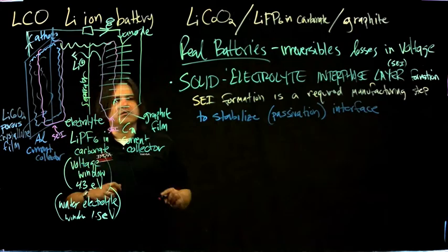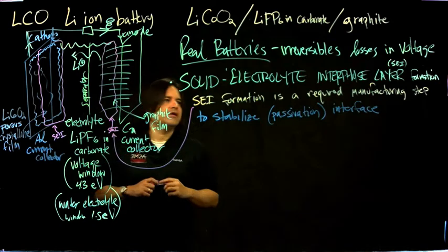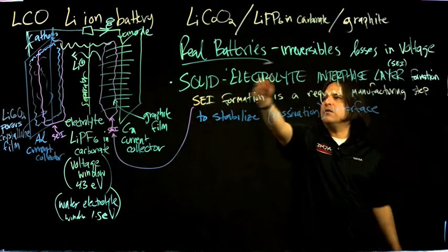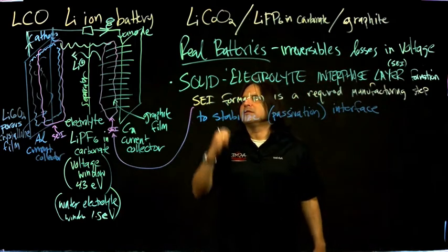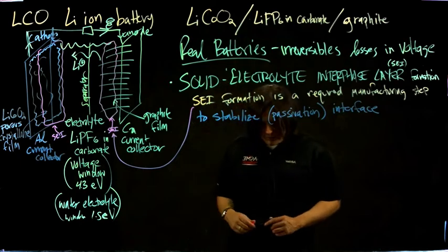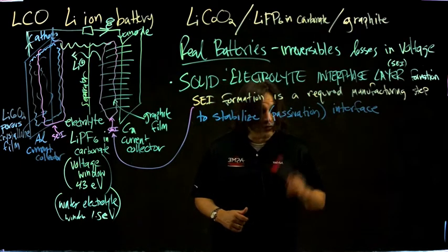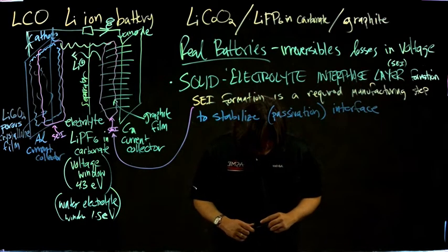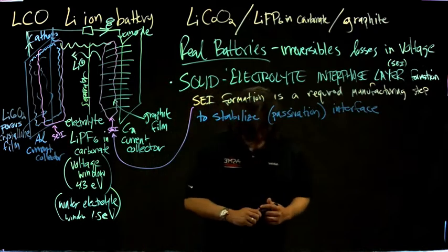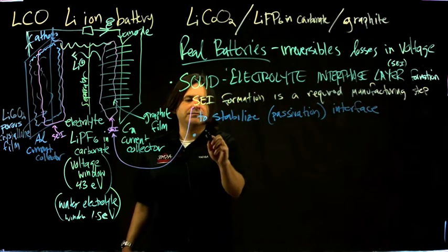You need to form those first. And once you form those, the voltage is going to be lower than the ideal case. So any real battery has to undergo that fabrication step. They have to literally form this layer. Then you can have capacity fade with cycling, meaning charge and discharge.